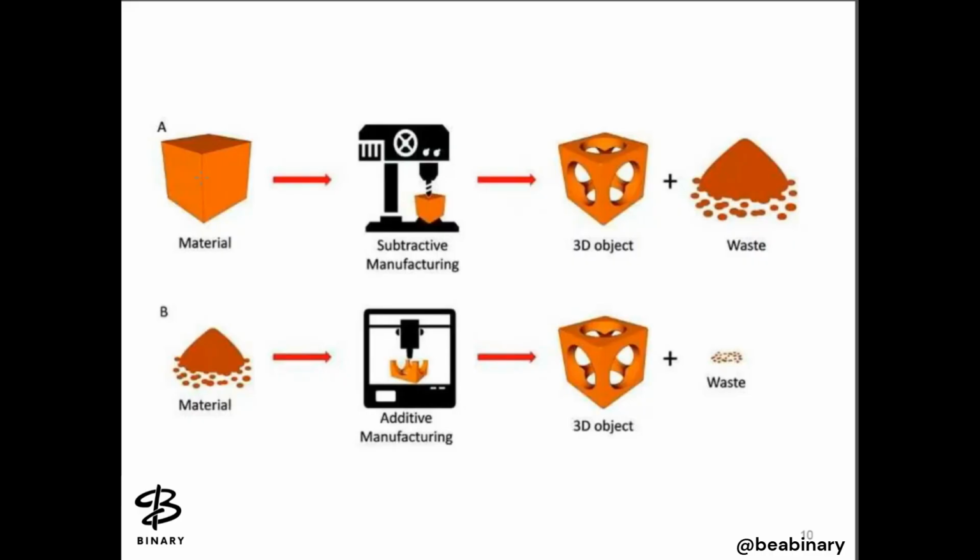But if we replace it with additive manufacturing, that is 3D printing, you see these powder particles. From this machine, the necessary amount of material is put into this object, which is designed by the CAD. Layer upon layer, wherever it is required, the material is pushed onto the surface, not like waste collected in a huge quantity while making the required 3D object.